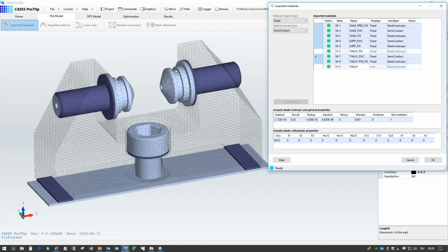The second problem is that once we have contacts, we will run during the optimization session at least once or a few times into a no convergence error related to the contacting surfaces. So this will be very difficult if we use usual contacts.